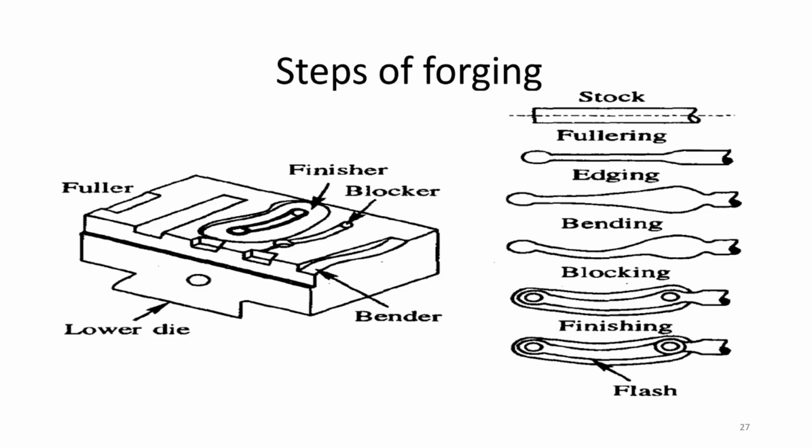Ma'am, I was asking about that the solid shrinkage and solidification are both different, isn't it? Solid shrinkage is actually after solidification, when the casting is coming down to room temperature. So the difference will be based on the thermal expansion value. We will be allocating that allowance value, isn't it? Yeah, so that is the solidification shrinkage, right, that you are talking about.